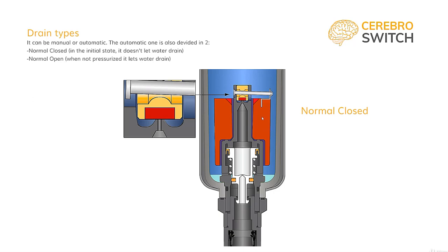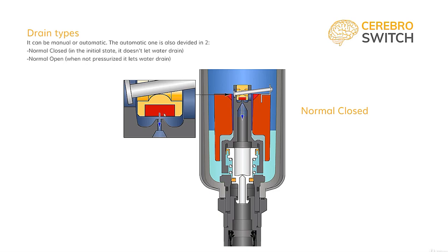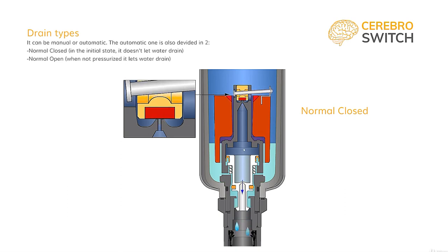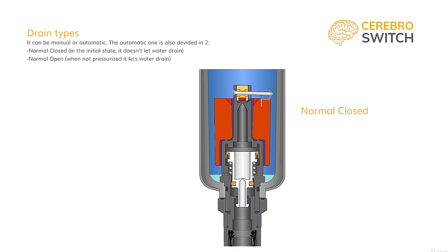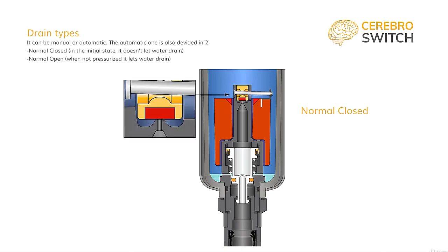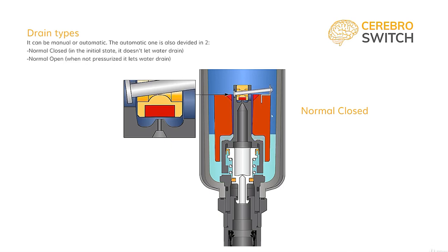It has this ring-shaped float, which will be raised by the water due to the buoyant force. The float operates a lever, which in turn opens up a simple valve, which regularly blocks the small air path. When it opens, air rushes in, pressurizes the chamber, and pushes a small piston against a spring. When moved out of the way, the piston opens up a flow path for the water. The water rushes out, encouraged by the pressure inside the bowl.